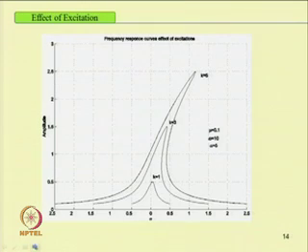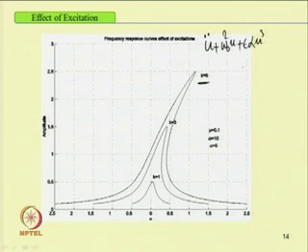Similarly, one can change different values of this k and find the response. Those things we will study in detail. So, this is a forced equation, that is, the forced Duffing equation, in the form u double dot plus omega 0 square u plus epsilon alpha u cubed equal to epsilon k cos omega t. In this case, by changing the amplitude, one can also get different types of response.